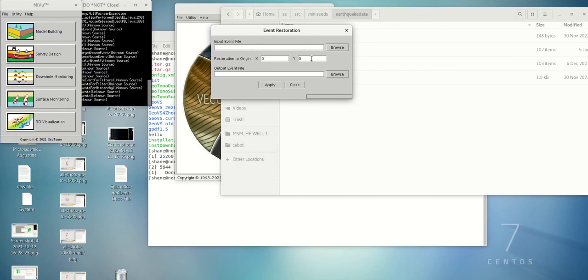I've never used it to put it back to relative, but I have processed a project in a relative coordinate system before, and then transformed it to a real world coordinate system. Usually, the reason I have to do that is if somebody changes their mind about what coordinate system they want it in to begin with. Sometimes if I already did it relative, I'll switch it to that. If they tell me that they don't know yet, or sometimes I've actually had to switch from one coordinate system to another as well. So it takes an intermediate step, but that's doable as well.